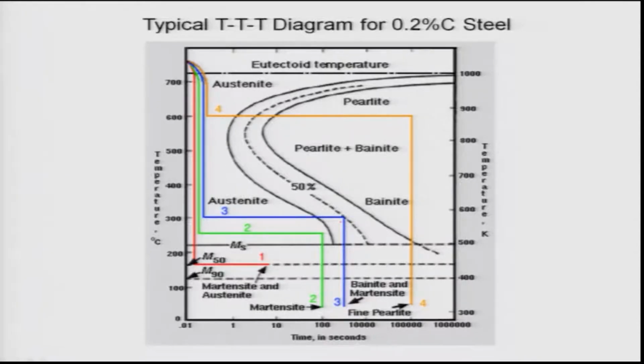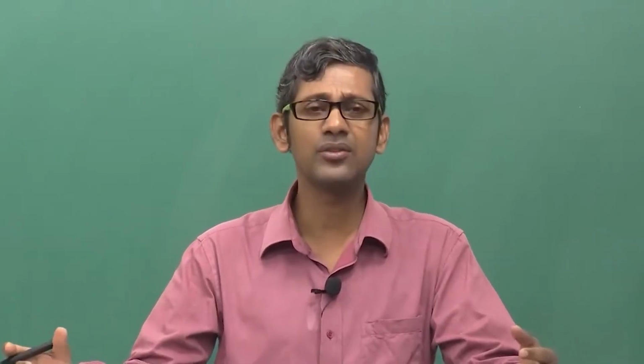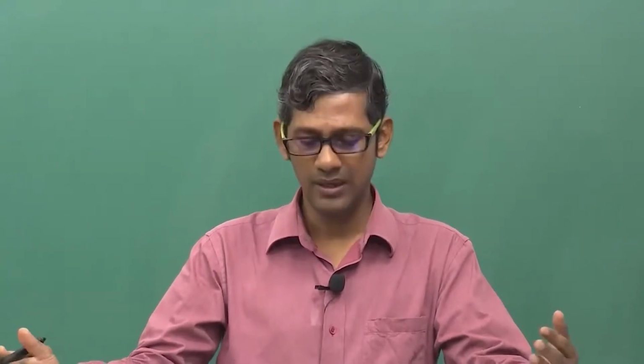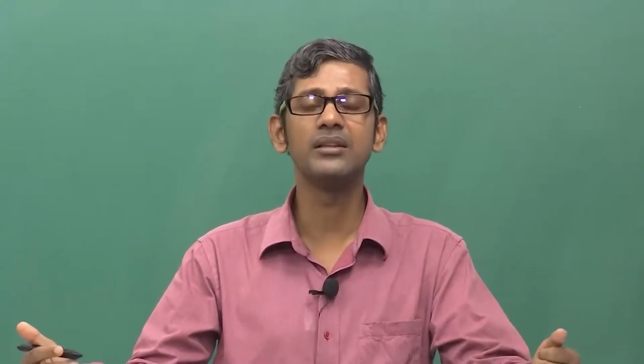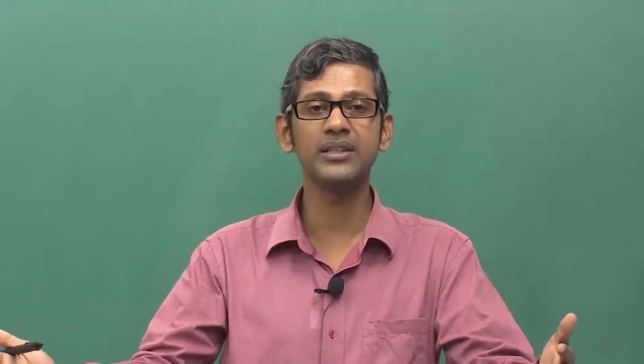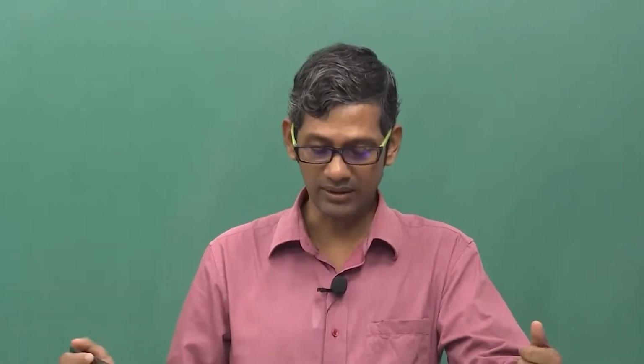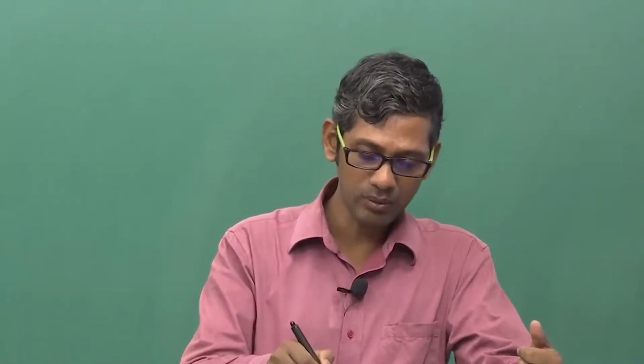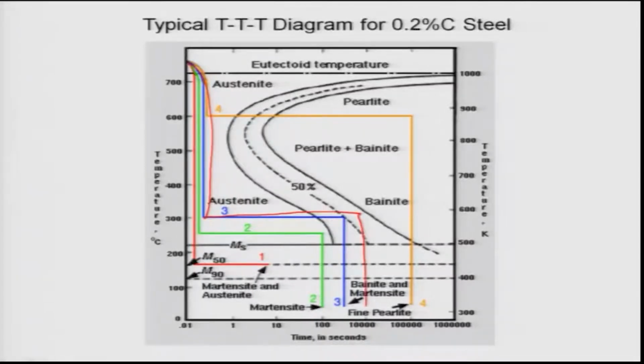That is possible because there are different requirements. As you know, the properties of the material depend upon the phases as well as their volume fraction in the microstructure. So these TTT diagrams still allow you to control both the type of phases and also the volume fractions. One can also have a diagram like that, you can cool it like this, keep it a little longer and quench it. By doing that, this is Mark 5, I can transform more austenite to bainite, and then the remaining, maybe 10 or 15%, will be transformed to martensite by cooling. Okay, that is one other way.